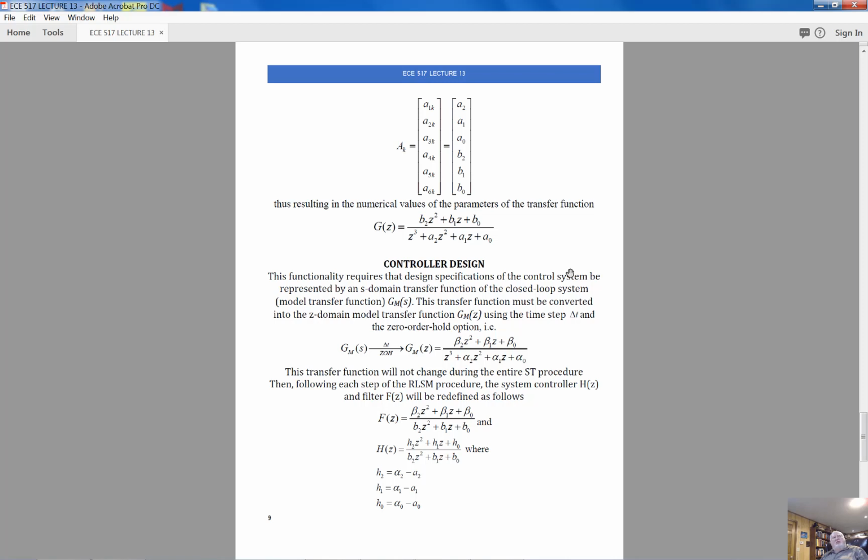And this is known as direct self-tuning, when we subject parameters of the controller to direct manipulation by our self-tuning procedure. In the case of indirect self-tuning, first we evaluate parameters of the control plant, and then we redesign the controller. So I have one more lecture for you on self-tuning, and this will be the direct self-tuning.